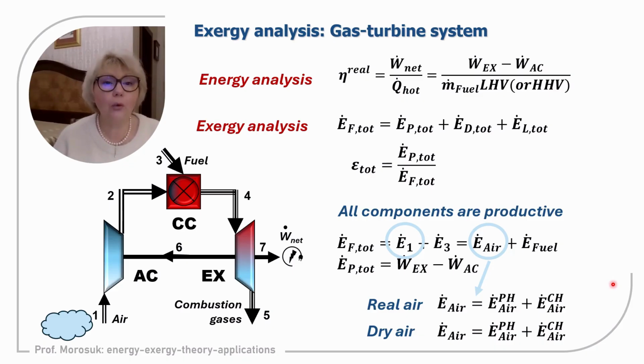So it means that air will consist of all gases that usually form air, and humidity will also be included. Or if it is simple calculations, or maybe even hand-made calculations, then we definitely will assume that air is dry, with no humidity, or we can even assume that it is theoretical air, meaning only nitrogen and oxygen, the two gases that form air. So for us, it is very important whether humidity is included in air or not.